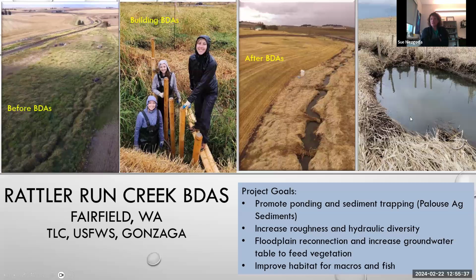And we have noticed that in this particular creek, the channel substrate was really good for pounding the posts. It was not quite a clay material, but more of a softer material that actually allowed the posts to go in and stay pretty stable. So we have done a good job on this one so far of creating ponding and attempting to raise the groundwater table back up, but it also takes time, right, to work through that.